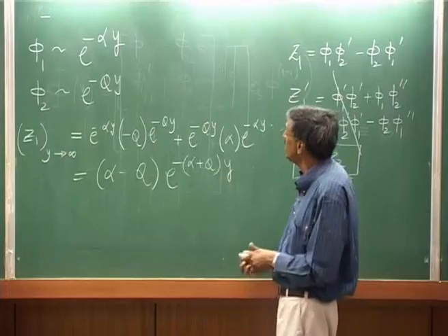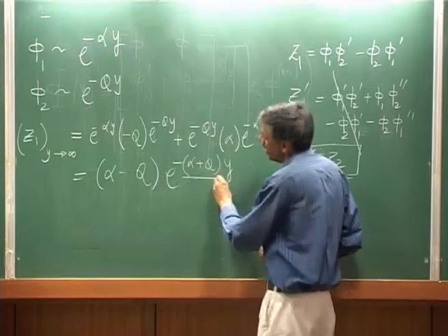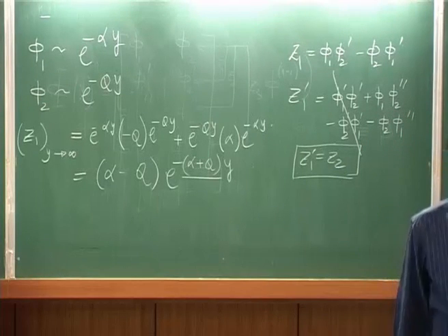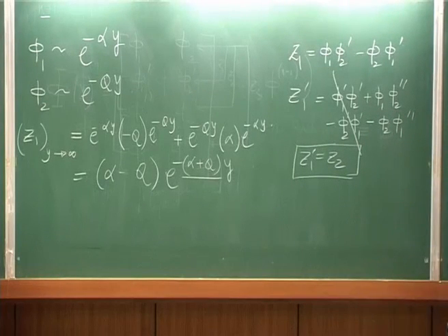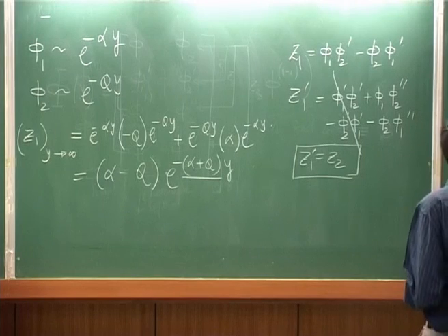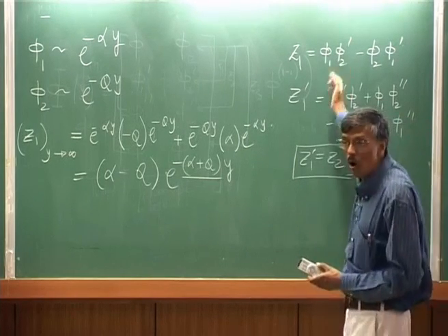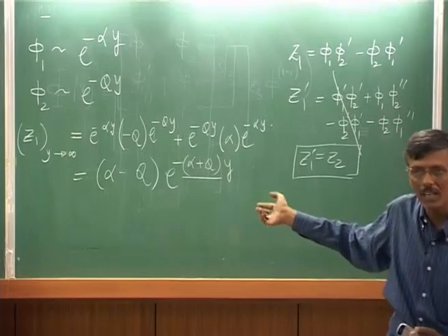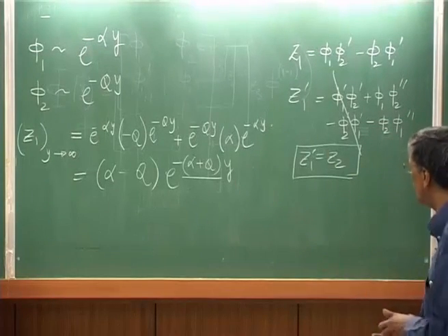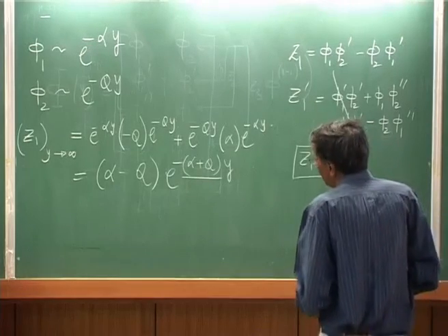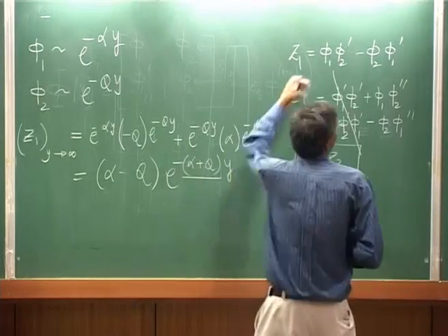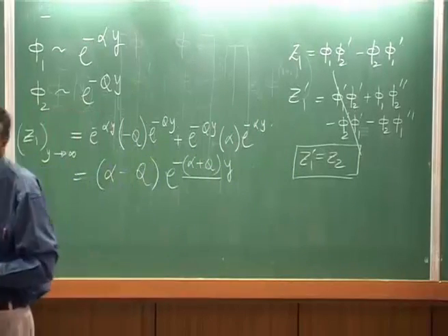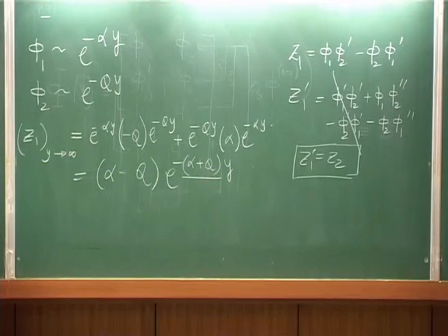Now, you see the variation is given by this quantity e to the power alpha plus q y with a minus sign embedded there. You would see that that would be the situation for all the 6 variables. All the 6 variables would have identical variation in the free stream. So, what it tells us is that by adopting this procedure, we have been able to remove the stiffness of the problem.